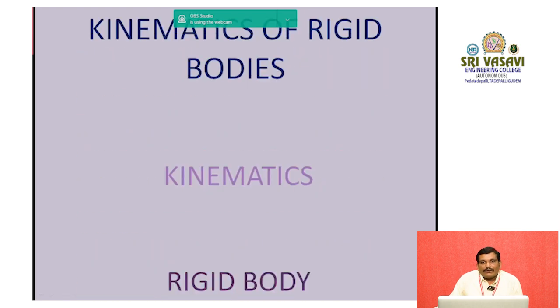In the kinematics of a rigid body, a rigid body forming part of a mechanism has a fixed length whatever its motion. Therefore, any 2 points on the body will remain a fixed distance apart. In the plane motion of a rigid body, all the particles move in parallel planes.